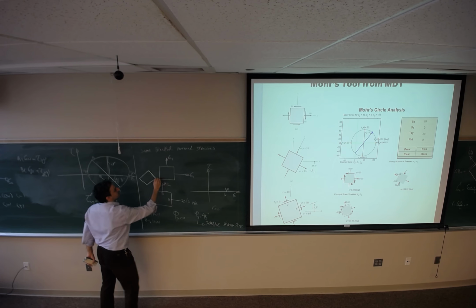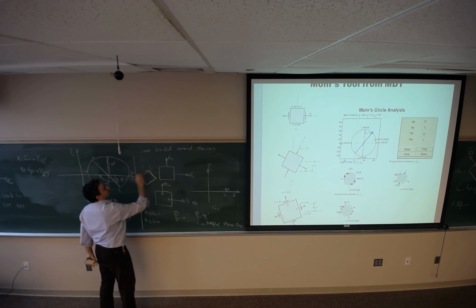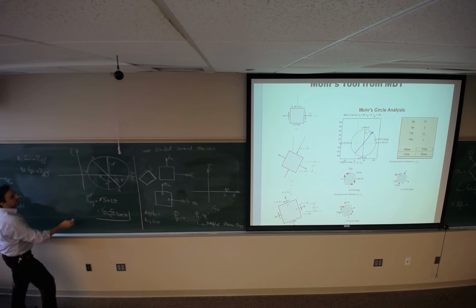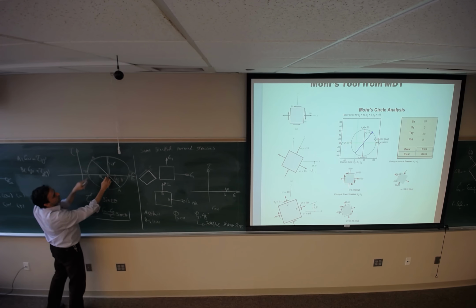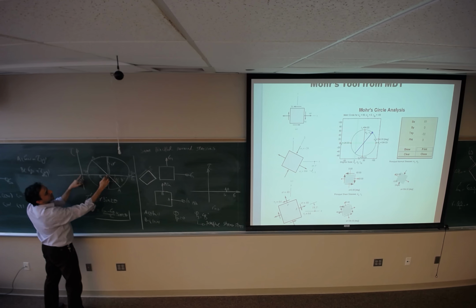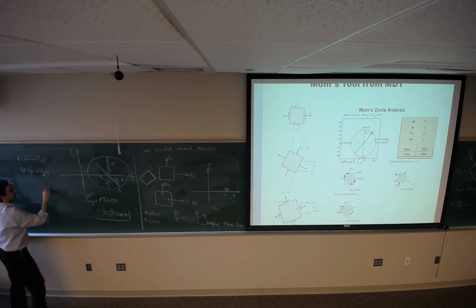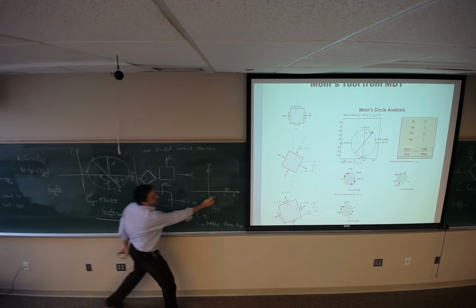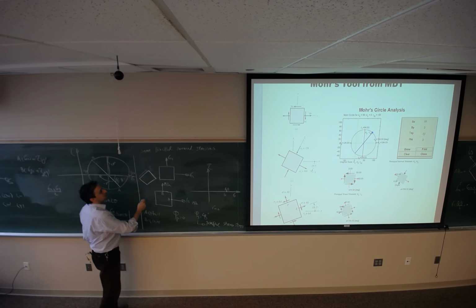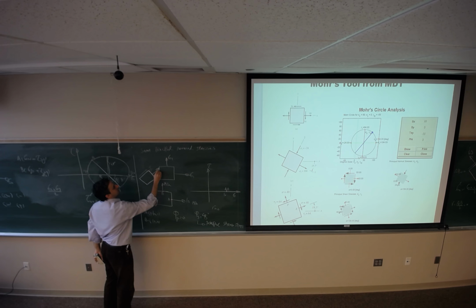So there is no shear stress right here. And at this location, the normal stress is going to be the center. The center is sigma x plus sigma y divided by 2, which is 10 plus 10 divided by 2, which is 10. So I will get 10, 10.